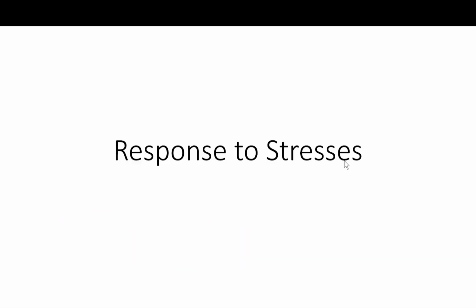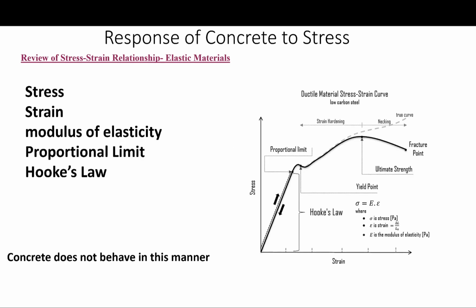Okay, after that we will move to the next module, which is the concrete response to stresses. As you know, before we study the hardened concrete mechanical properties such as strength and modulus of elasticity and all that, we need to understand how concrete responds to stress. Concrete, as you can imagine, is really a complex heterogeneous material. It's not a homogeneous material like steel, where the properties are easy to understand.